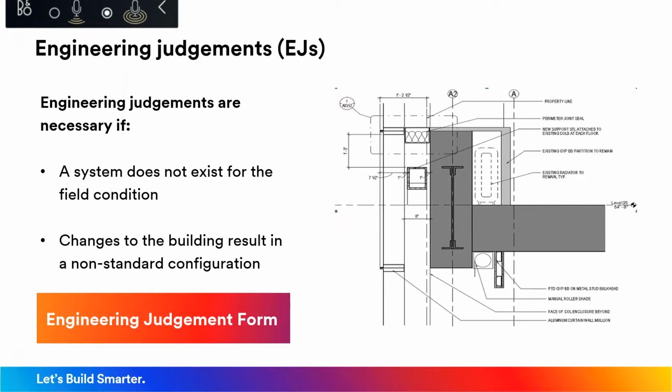If for whatever reason, maybe it's a retrofit type situation that's not very common, and there are no systems that exist, get with the manufacturer, and they'll work through an engineering judgment process and provide you documentation that you can then seek approval with out on the job site.